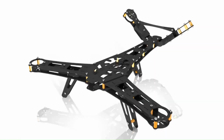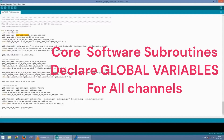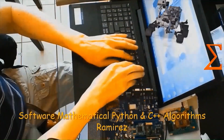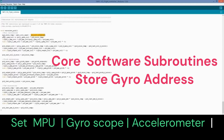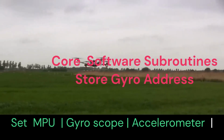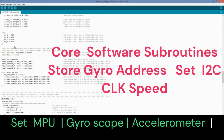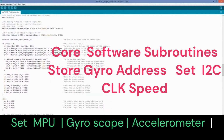Take multiple gyro data points, calibrate and read the gyro output. Include the roll, pitch and yaw values. Now divide all the above values by 2000. So wait until the receiver is active and the throttle is set to lower positions.